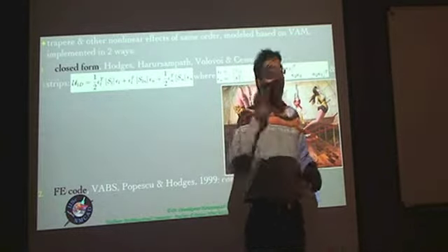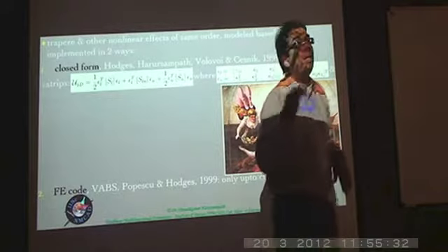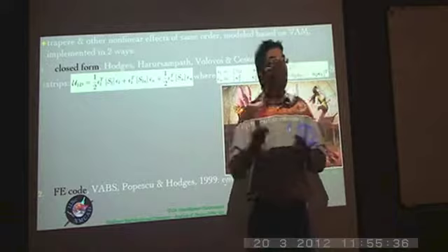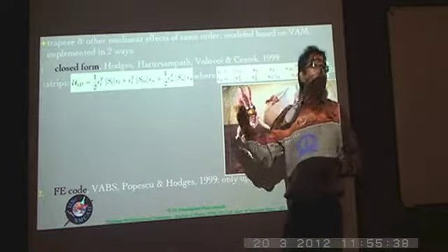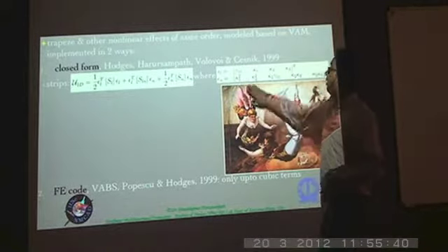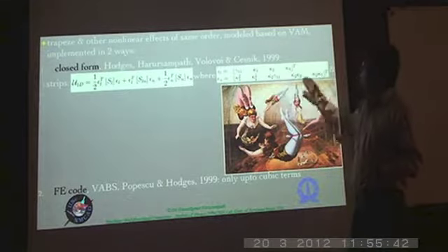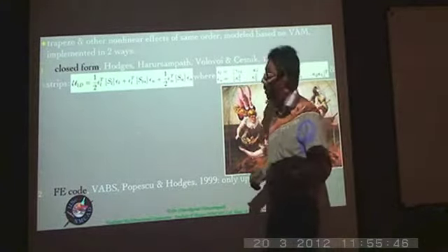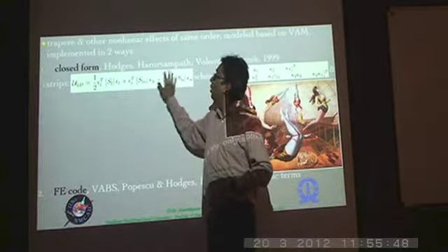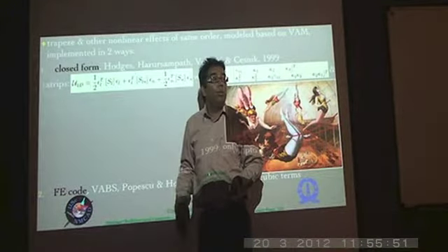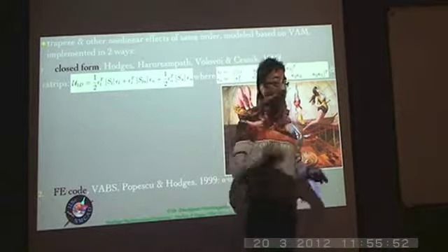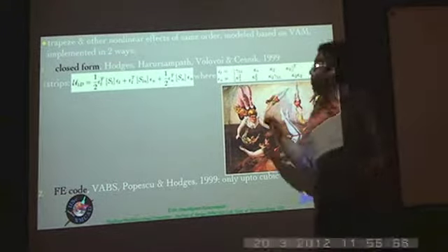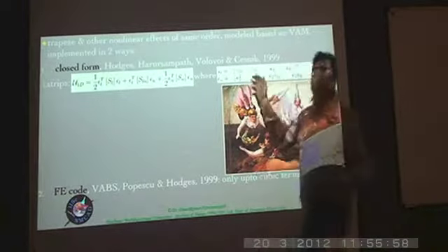And so therefore, if and only if kappa 1 and/or kappa 2 are present, then you will have the nonlinear effects coming into prominence. Otherwise, if both kappa 1 and kappa 2 are 0, epsilon n itself is a 0 column matrix, and these two terms will not contribute anything to the one-dimensional strain energy density. And this is very easy to observe in a thin strip, but the thin strip results are the most complicated.